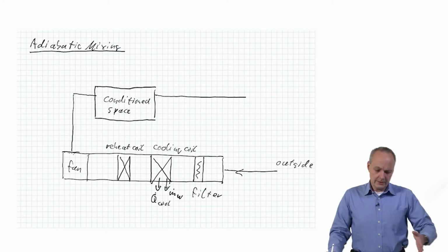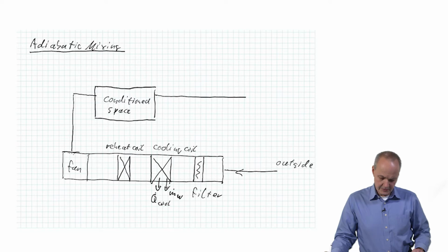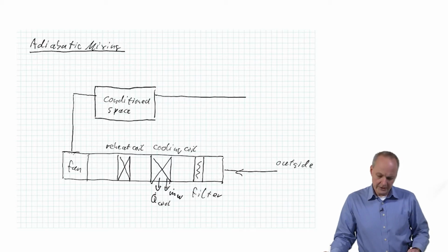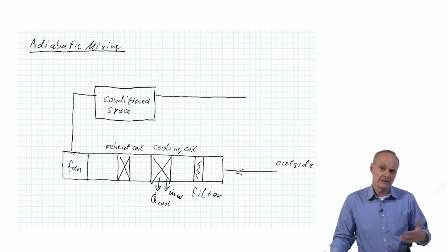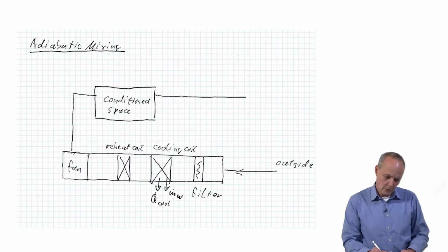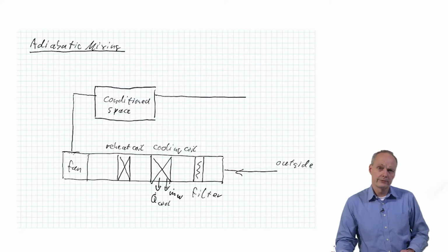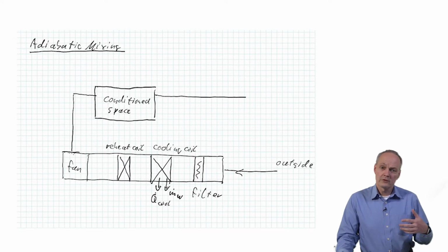Okay, so you can use this kind of an air handling system for summer cooling situations, but also for winter heating situations. You would just not run chilled water through your cooling coil and instead run only hot water through the reheat coil, and that would likely do it in order to get you air for winter heating conditions. So in summer, typically we want the air to go into the fan and then be brought into the room at temperatures of around 55 degrees Fahrenheit. In winter, for commercial buildings, we may let this go up to 65 degrees Fahrenheit.